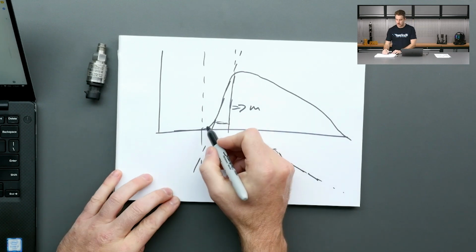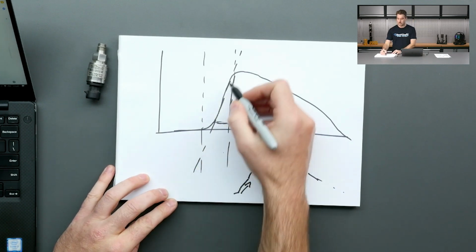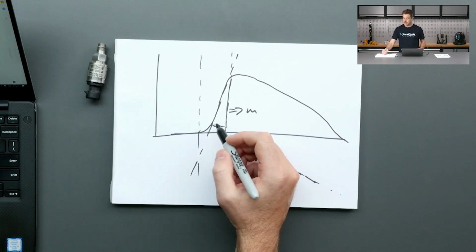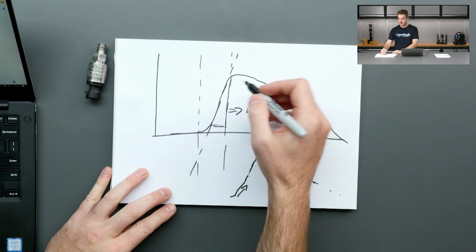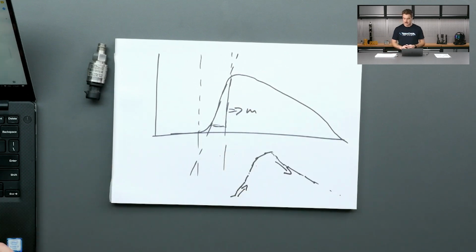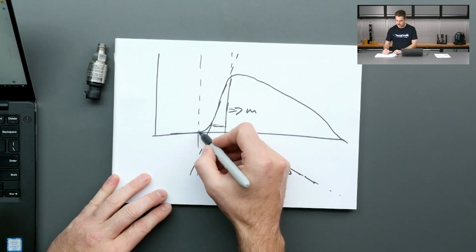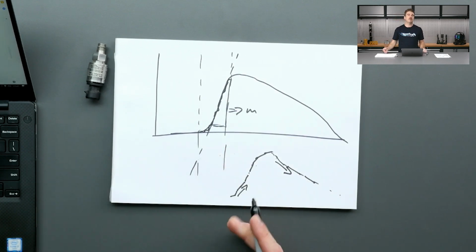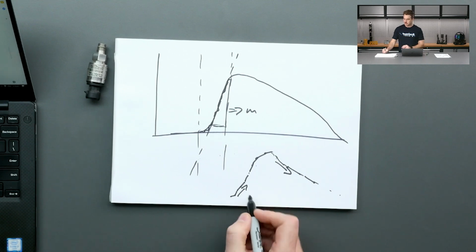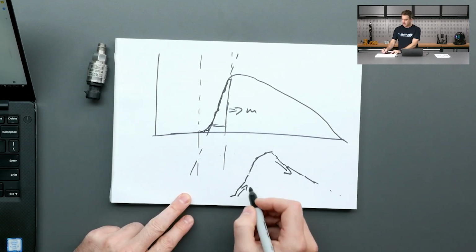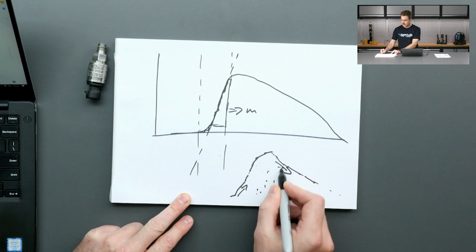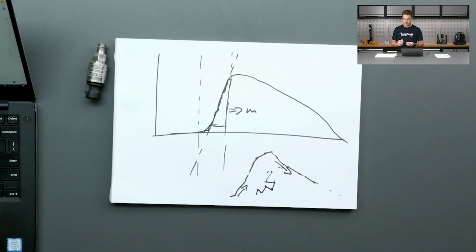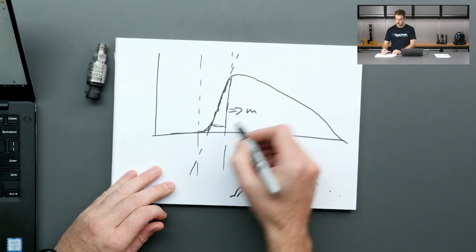That's great. The next thing we want to do is take the derivative or the average slope of this line as well. We don't have to take the average; there's all sorts of different ways you can calculate it. But one of the first things I do normally is that you'll see the brake pressure data usually has some messiness to it. The problem with that messiness is it does tend to stuff up the derivative calculation, because when it's doing these little slope calculations up here, if you've got very messy data like this, these slope calculations can go crazy like that. So what you first usually want to do is smooth that signal.